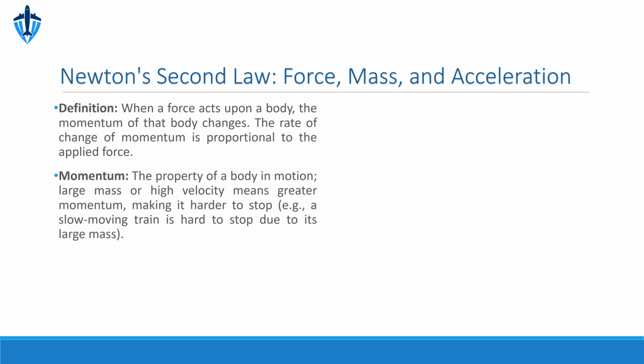This configuration gives it a mechanical advantage of 2, meaning it effectively magnifies the force exerted. For instance, if you're lifting a 100-pound object, you would only need to apply 50 pounds of effort. However, this force reduction comes with a trade-off. You'll need to pull the rope twice the distance the weight needs to travel. So, pulling 4 feet of rope will only raise the weight 2 feet. This figure illustrates this single movable pulley system.